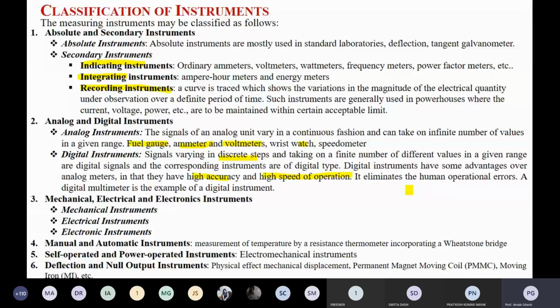Maybe you are going to measure 10 kilovolts and you have a 600 volt voltmeter. You don't know the exact value of the 10 kilovolts, because it was initially unknown. If you connect the 600 volt voltmeter to the 10 kV system, your voltmeter will be damaged. There will be chances of damage.